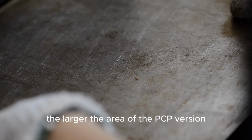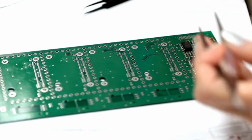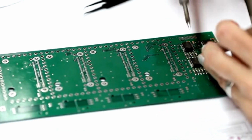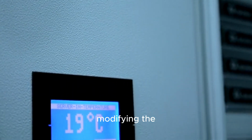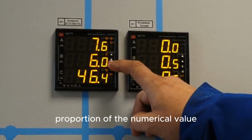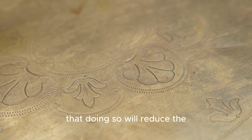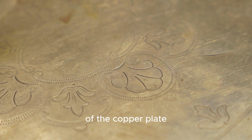The larger the area of the PCB, the easier it is to suffer thermal expansion and deformation in the subsequent SMT high-temperature links. The thermal expansion deformation can be solved by modifying the resin in the copper-clad plate or by reducing the content proportion of the resin. It should be noted that doing so will reduce the flame resistance and chemical properties of the copper-clad plate.